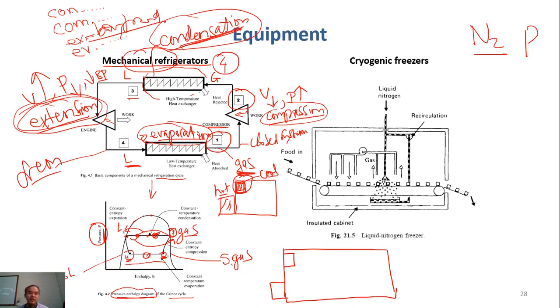Because you see there is piping running around. So there are always 2 copper pipes connecting them. If you observe at home, you will see that one pipe is smaller than the other: one larger, one very small. The small one is for liquid, the large one is for gas. You go home and check, you will see.